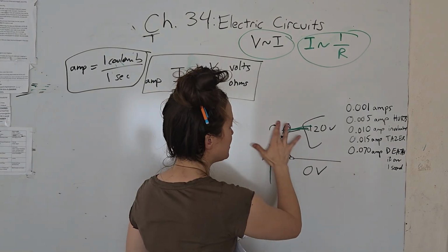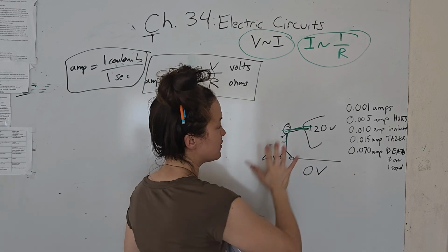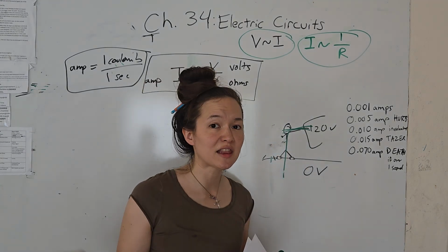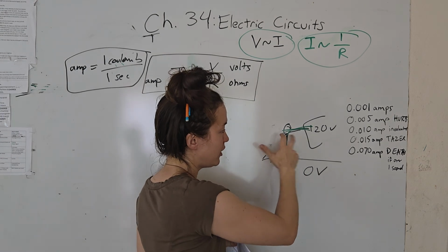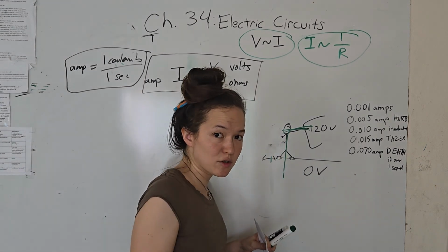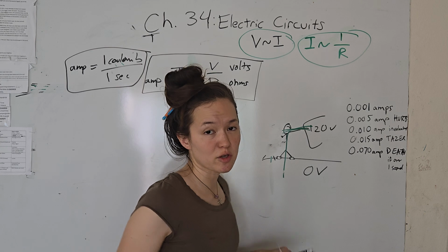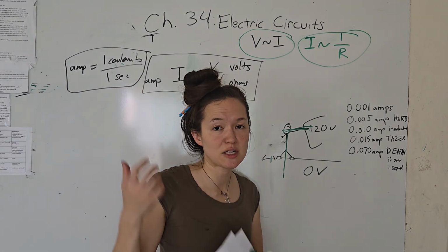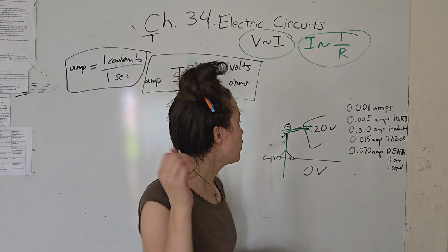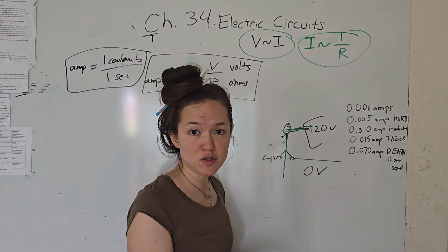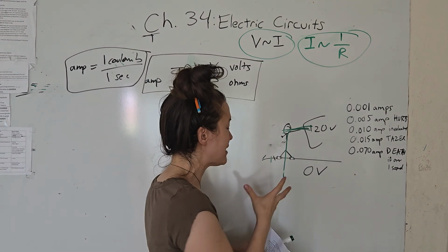So when you see someone being electrocuted, you want to get them away as fast as possible. What you usually want to do is hit them with a non-conductive material. Obviously, if you hit them with a metal bar, then you become part of that circuit. You're being electrocuted too. In the old days, electricians used to have a buddy with a 2x4, wood, because wood is not very conductive, to whack them with if they start getting electrocuted. So you want to grab something non-conductive.